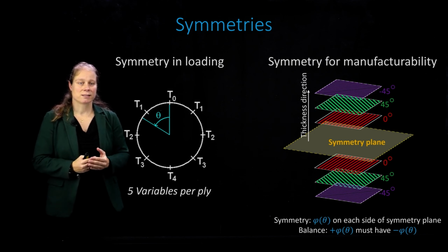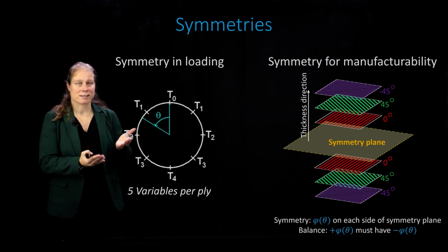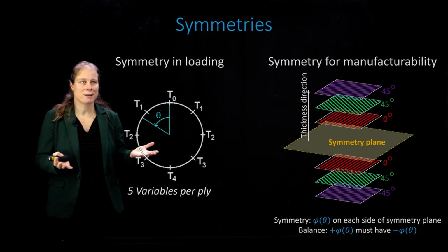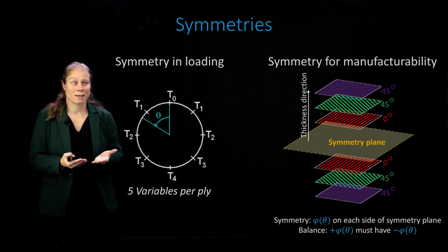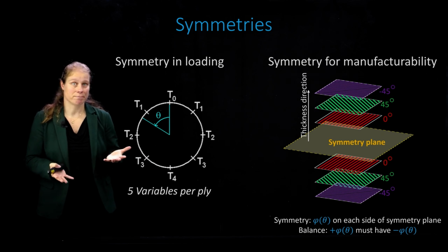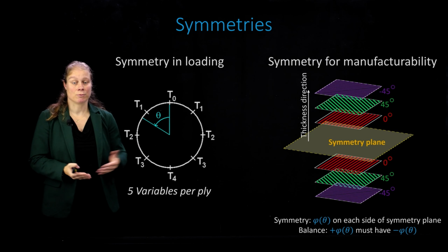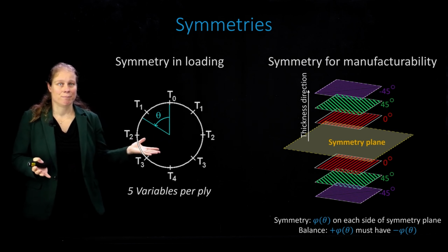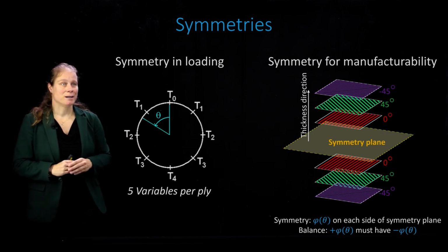And the reason for that is if you take a flat sheet and you don't apply this symmetry and you cure it, kind of bake this composite in the oven or in the autoclave, it will come out as a potato chip. So you want your structure to be flat, and so you don't want it to be a potato chip. And this is something that people who've taken a class on fiber reinforced composites should be familiar with.